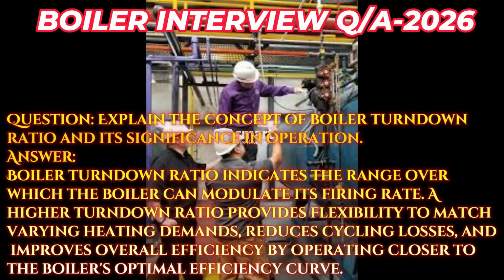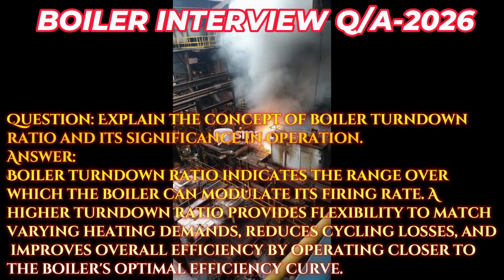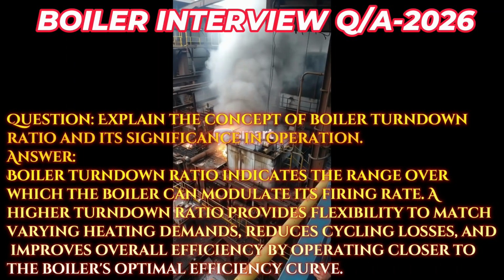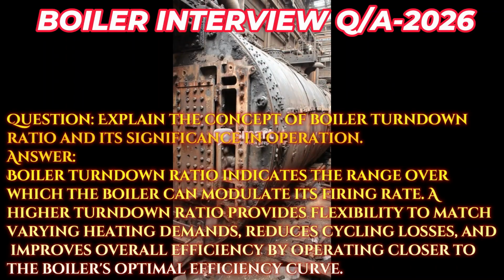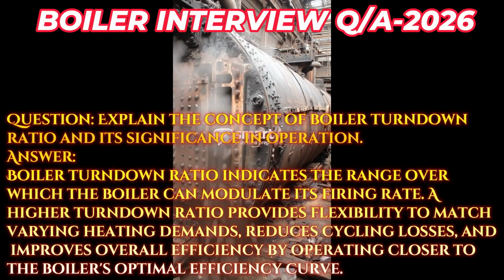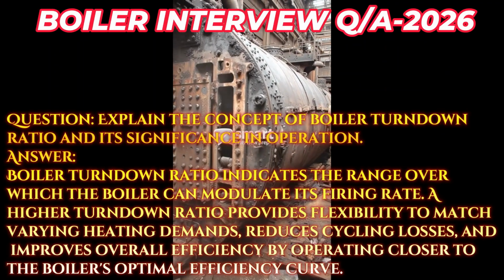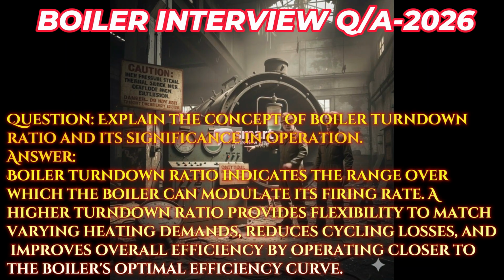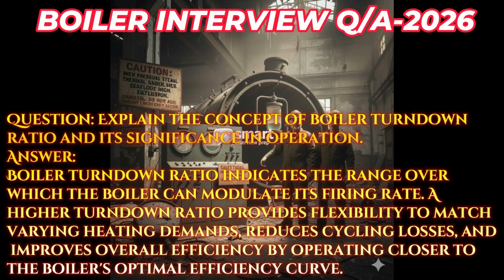Question: explain the concept of boiler turndown ratio and its significance in operation. Answer: boiler turndown ratio indicates the range over which the boiler can modulate its firing rate. A higher turndown ratio provides flexibility to match varying heating demands, reduces cycling losses, and improves overall efficiency by operating closer to the boiler's optimal efficiency curve.